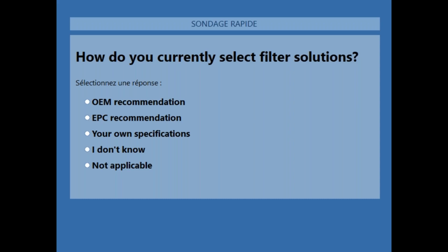What I found out, Jeremy, is that the OEMs will specify a minimum requirement, and that could be based on anything such as the filter efficiency, but also include things such as the hydrophobicity of the filter media, possibly the media area included into the filter construction itself, and burst strength requirements are typical in the gas turbine industry to ensure that you're not going to have any breakdown and filters getting ingested into the turbine.